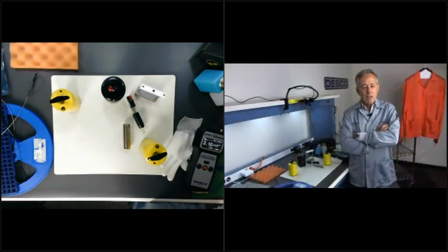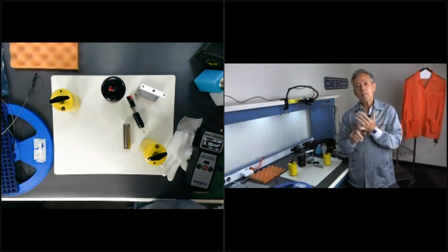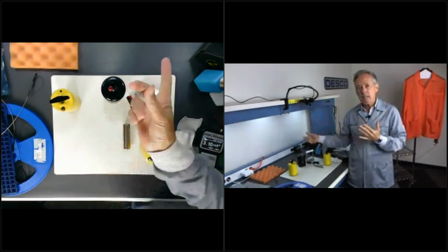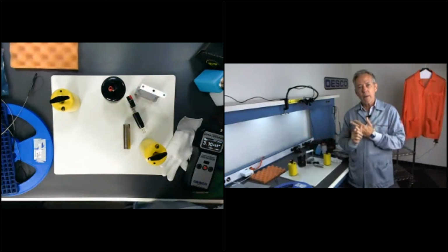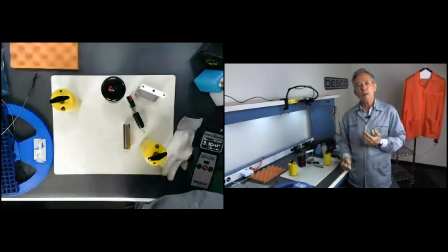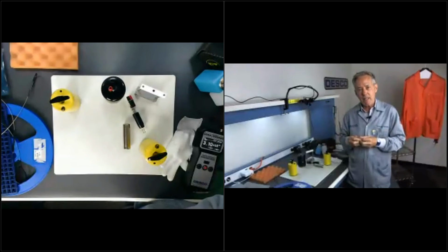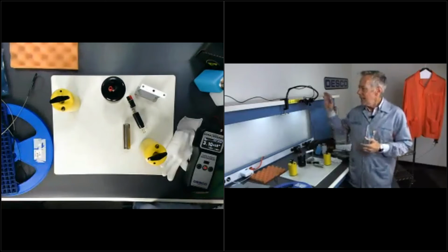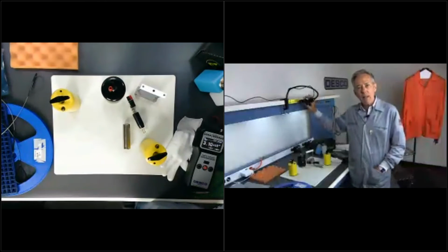Right. So when it comes to what you use for your ESD ground in your static control program, there are 3 acceptable grounds. There's the AC, or building's electrical ground, equipment ground. There is an auxiliary ground, and that's typically a separate 8-foot ground rod driven in the earth, and then my static control grounds are attached to that as my ESD ground. There's also what we call equipotential bonding, and that is, let's say this bench was sitting out in the middle of nowhere in a warehouse, and there wasn't an AC outlet in sight.